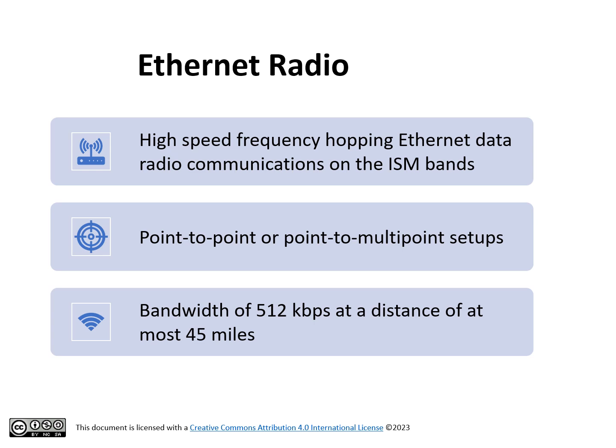The J-Series Trio radio, manufactured by Schneider Electric, employs several layers of security. The first layer uses the network name for deriving the hopping sequence. The second layer of protection uses the serial numbers as trusted labels. The third layer is through the use of a 256-bit AES encryption key to encrypt the data that is to be transmitted.